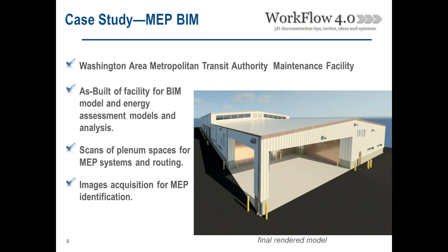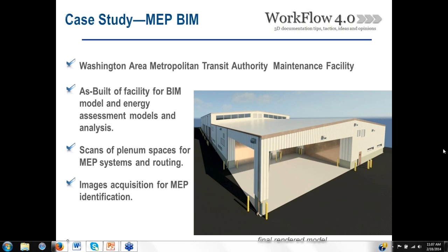One of the more interesting things was the ability to integrate photographs into the BIM model via hyperlinks. Our VZ400 allows us to capture photographs, and it has a flash on it. So when you put it in the plenum spaces, you can get a good idea, past just what the point cloud has to offer, of what's actually happening in the plenum spaces.